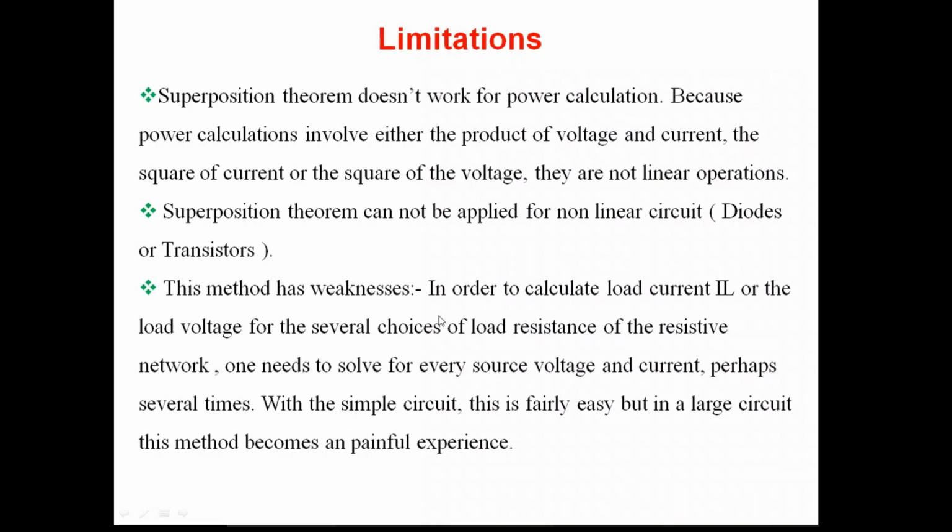And this method has a weakness. In order to calculate the load current IL or the load voltage for several choices of load resistance in the resistive network, one needs to solve for every source voltage and current, perhaps several times. With a simple circuit this is fairly easy, but in a large circuit this method becomes a painful experience, because every time you have to do the complete calculations for as many times as there are sources. So with complex circuits, it is a painful experience when we use the superposition theorem.